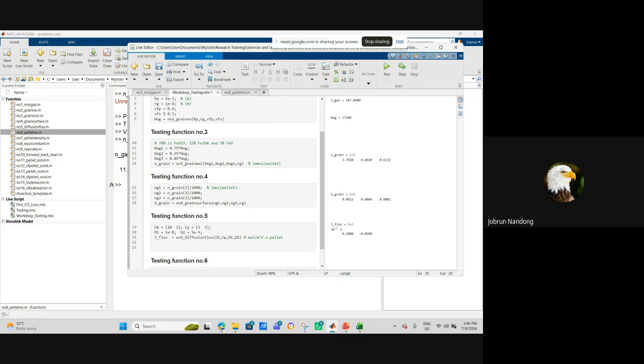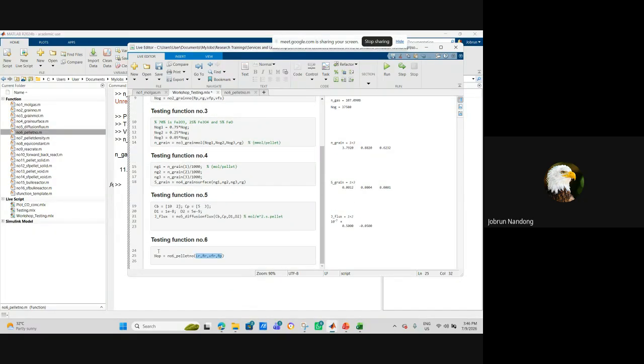If we haven't got the things on the top here, we need to specify it first. So let me specify the length of the reactor section. Let's say the length here is maybe 0.25 meters. Unit in meters. Radius of the reactor: although we have many pipes, we can just lump them together and see a single reactor. So this one may be 0.5 meter, say.